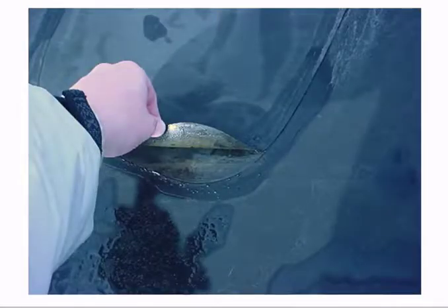Craig, we've got failing patches here. Yeah, and here, it looks like it's an older EPDM style roof, and they didn't have the primers and the cleaners and the self-adhering membranes, and it looks like this has just popped up over time with weather. But your typical contractor, what I see a lot is coming in here and they'll just recaulk that patch down. To do that right is to cut away any of that loose patch and use the modern technology with our new equipment and the new products and do a large scale patch over that, up to industry standards.